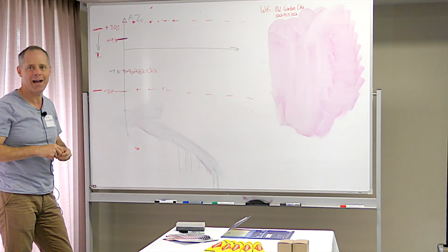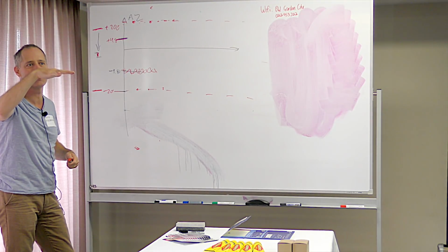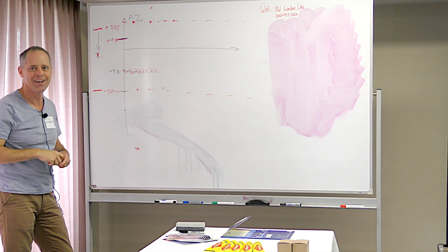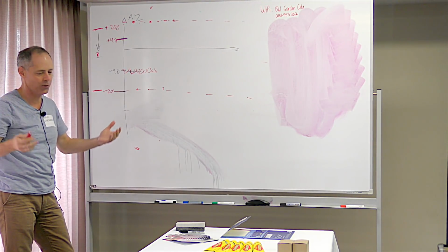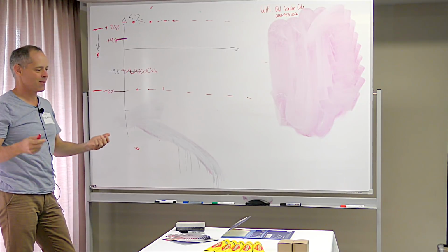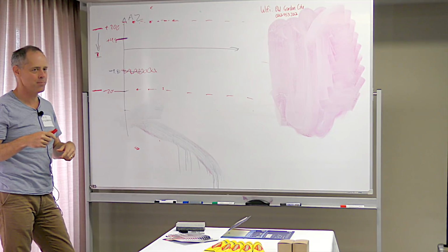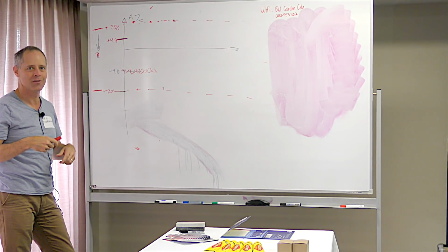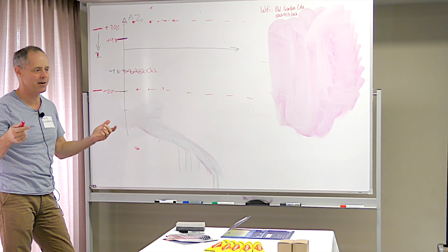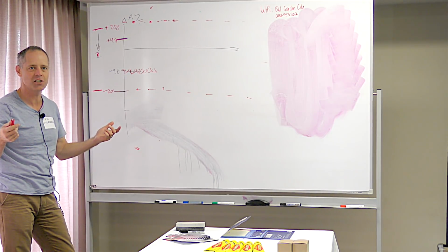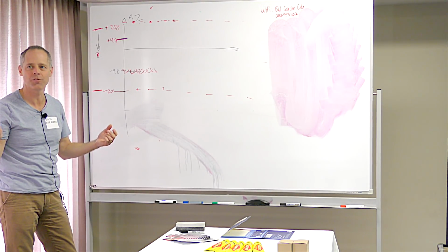Now, how do you measure a 0 accelerometer value? Under what condition do you get a 0 accelerometer value? Free fall. So the inertial navigation system goes, I'm free falling. And then the EKF updates come in, and the baro disagrees and GPS disagrees. But it continues, and then eventually the baro and the GPS are outside the innovation limits. It stops using the baro, stops using the GPS.